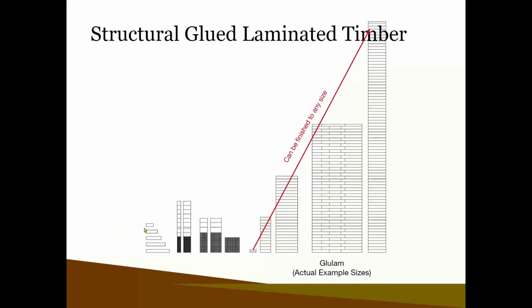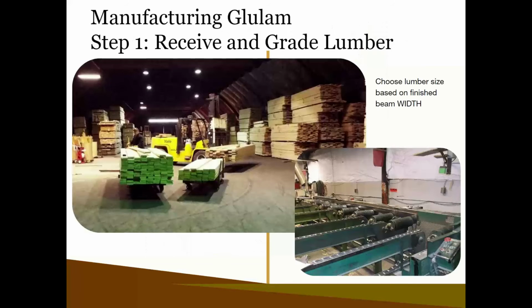The slide here is to show that we're taking nominal lumber right here. This is like 2x4 to 2x12, and we're manufacturing custom projects. So this is what you see for lumber. These are LVL standard sizes. These are standard sizes available for PSLs, and then this is what's available for glulam. This right here is 24 inches wide by 60 inches deep. And this really tall one right here is 8.5 inches wide by 9 feet deep. So with glulam, your limitations really only come with shipping restrictions and the facility from which you're getting your product.